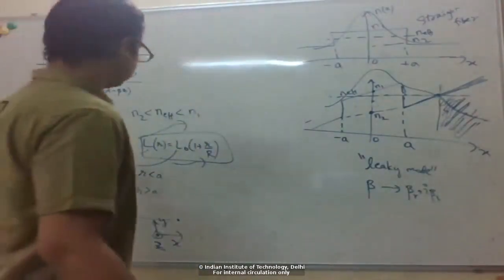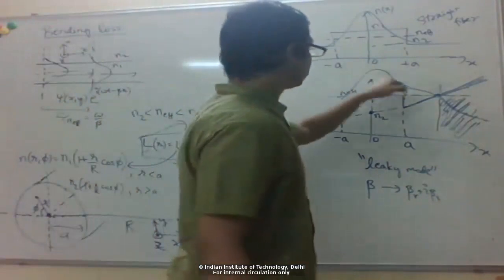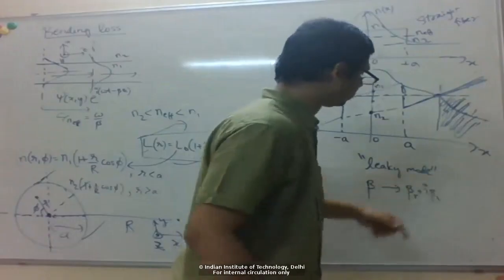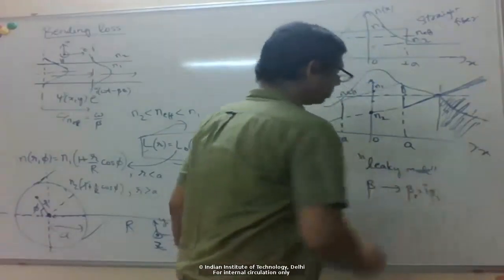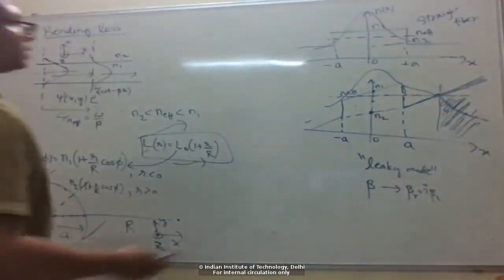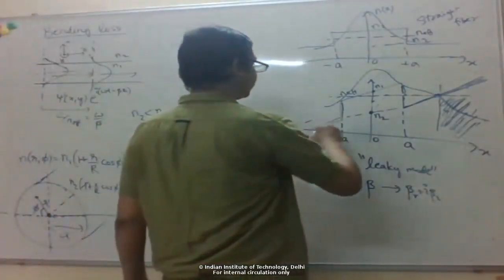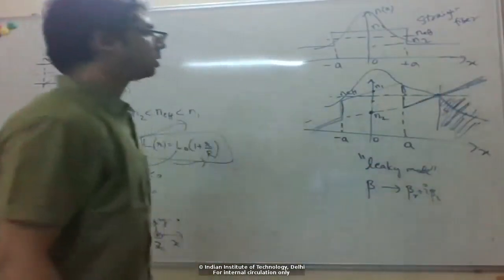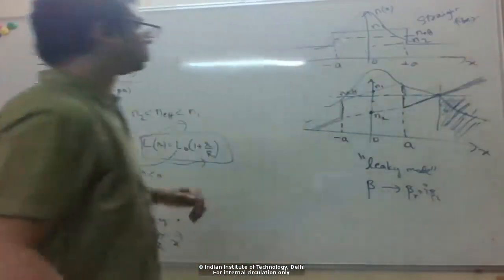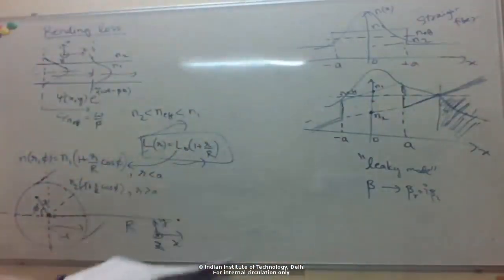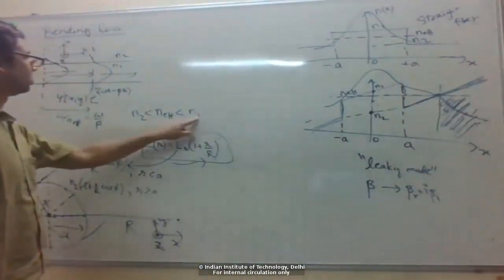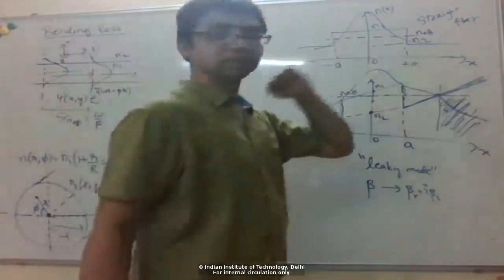But basically the point is that you take this kind of refractive index profile, then you calculate the leaky mode, and then you find out what the imaginary part of the propagation constant is, which gives you the loss factor. So you can see for this kind of refractive index profile, there cannot be a well-defined guided mode because the cladding index keeps going up. You cannot have confinement because you cannot satisfy this condition for all points in space.